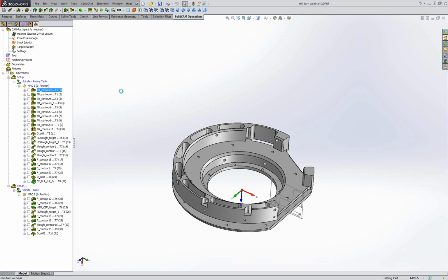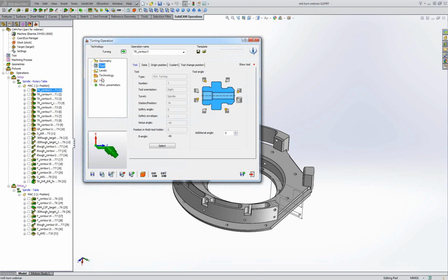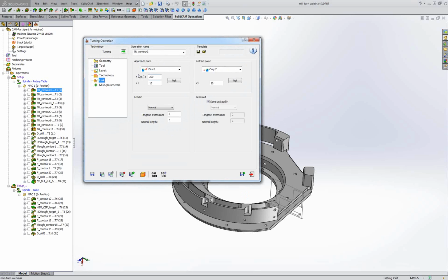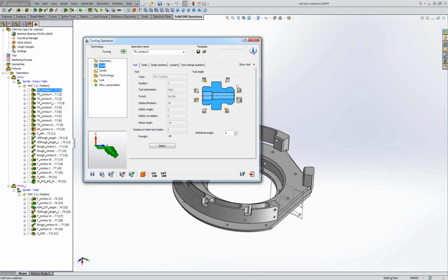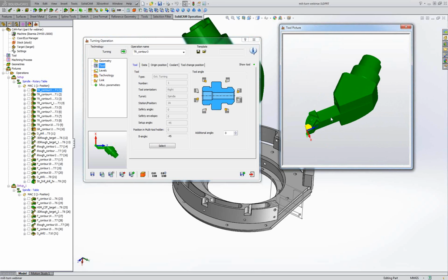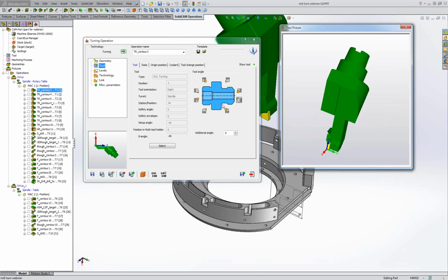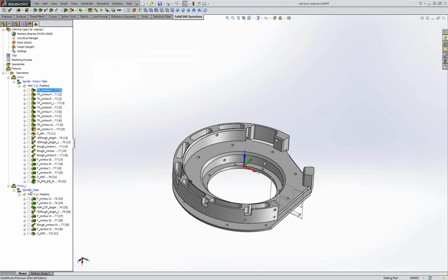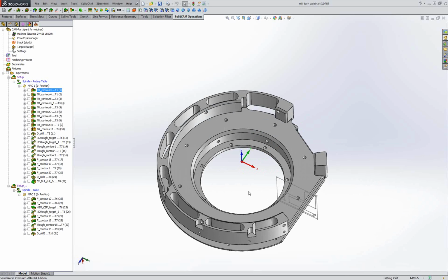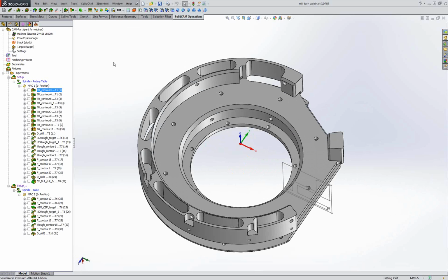So what we did today is to see how to make the best use of tool mounting in turning operations and approach and retract points, very useful options. Use tools with STL and chunk. It's very easy to download them, and this is free from the tool manufacturer website. And this way you have a real simulation with real collisions. You can detect real collisions. Define a second setup, move the part to the milling table and continue to work. That's the standard procedure on milling machines with turning option. And I finish here, I think, yes.